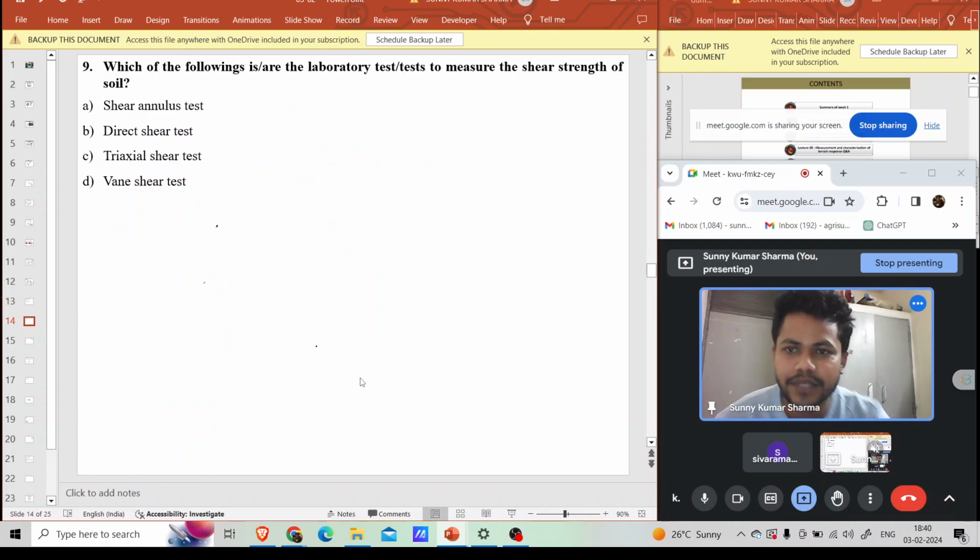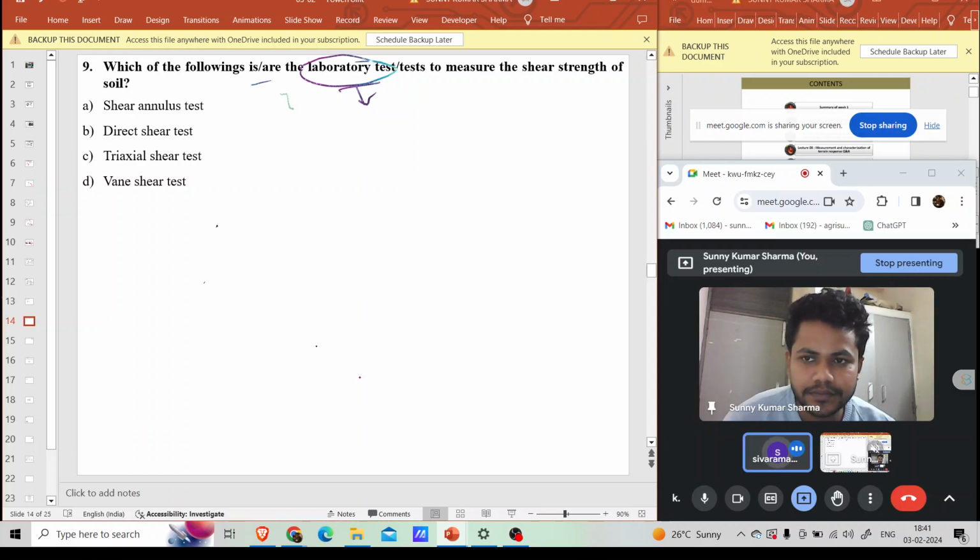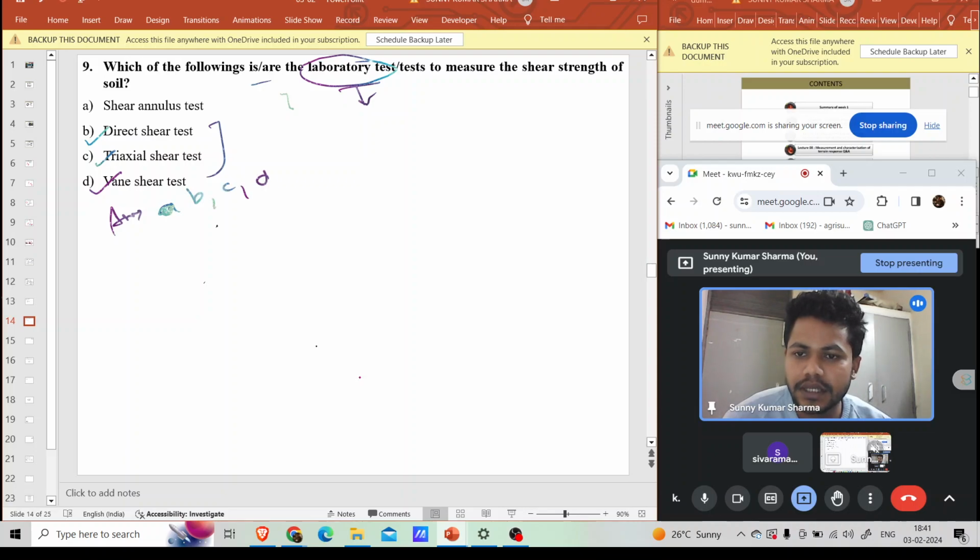Okay, next question. If you have studied that NPTEL course, you will tell it simply. Theoretical question: which of the following is or are the laboratory tests to measure the shear strength of the soil? What all tests come under laboratory tests? Direct shear, triaxial, and vane shear, sir. Okay, that is correct. So the answer is B, C, and D.